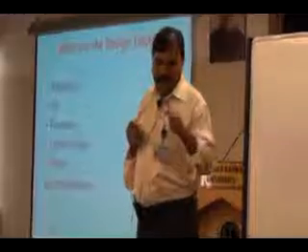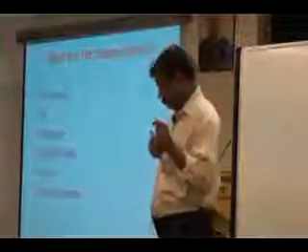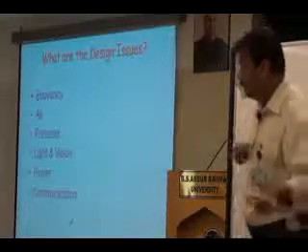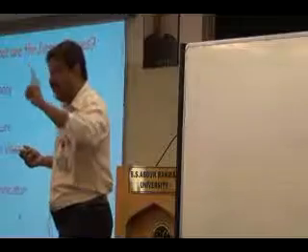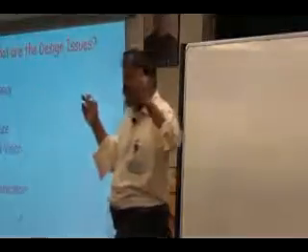It is made of a steel plate about 12 to 15 mm thick. 12 to 15 mm thickness is required for even a pressure of 12 bar. For every 10 meters, the water pressure alone is going to increase by 1 bar.